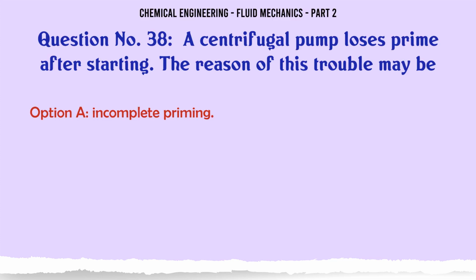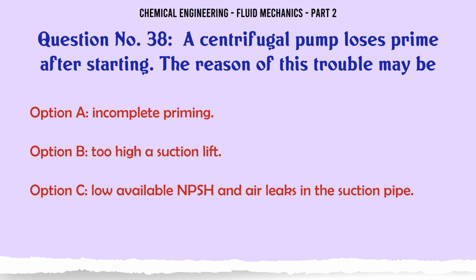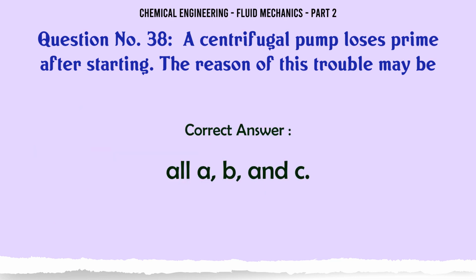A centrifugal pump loses prime after starting. The reason of this trouble may be A. Incomplete priming, B. Too high a suction lift, C. Low available NPSH and air leaks in the suction pipe. D. All A, B, and C. The correct answer is all A, B, and C.